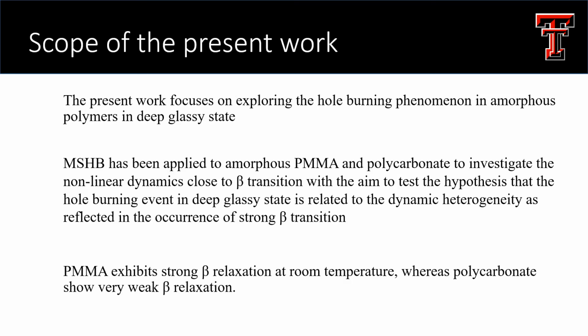Now that we have understood the necessary background, we now look into the current work. So the present work focuses on exploring the hole burning phenomena in amorphous deep glassy state. Mechanical spectral hole burning has been applied to amorphous PMMA and polycarbonate to investigate the nonlinear dynamics close to beta transition with the aim to test the hypothesis that the hole burning event in deep glassy state is related to the dynamic heterogeneity as reflected in the occurrence of strong beta transition.